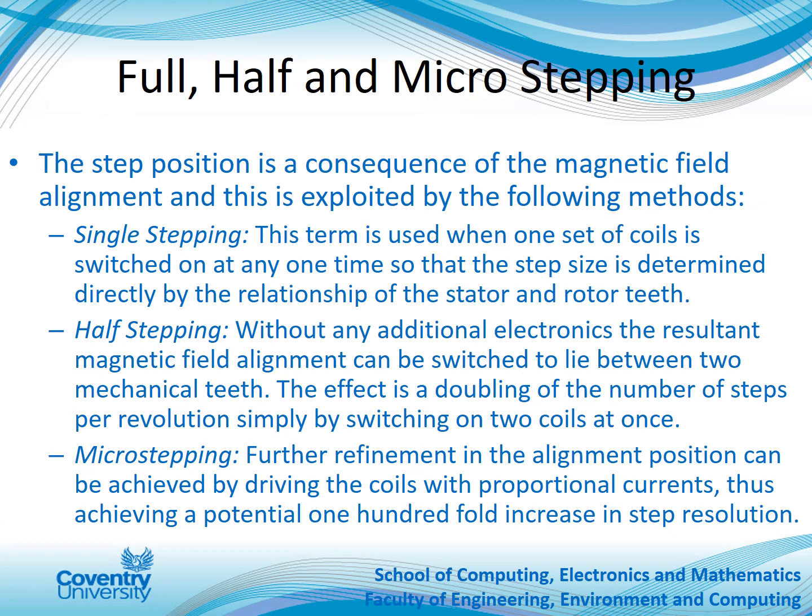Microstepping, as I said before, is where you vary the voltage on each coil, and you can then go to fractions of a degree by making the rotor go between the coils. It's a really useful way if you want really fast precision, and we can go over some of that in the tutorial if you want me to elaborate further.